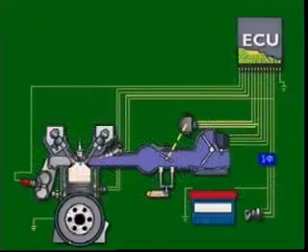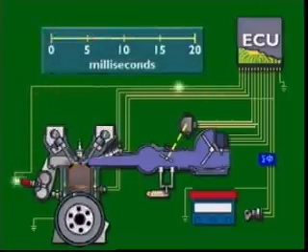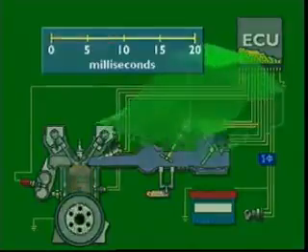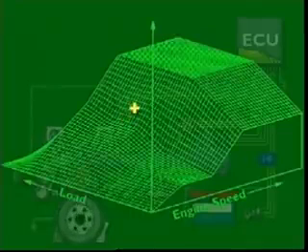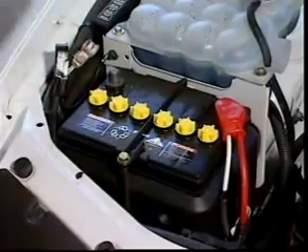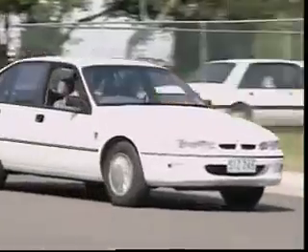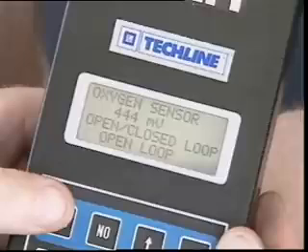However, if fuel pressure is less than when the vehicle was new, feedback from the oxygen sensor can cause the lambda control to increase injection time. The control unit learns the new time and stores it in its memory for future use in that condition. If the battery is disconnected or memory is lost, the settings revert to the manufacturer's programmed specifications. And the vehicle then has to be driven in a range of conditions to let the control unit, in effect, relearn the engine's fuel settings.